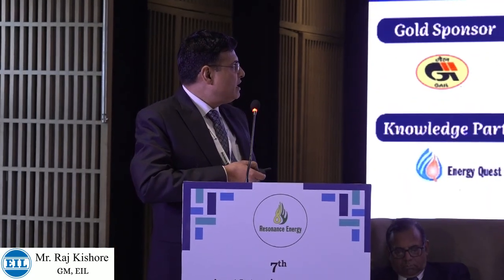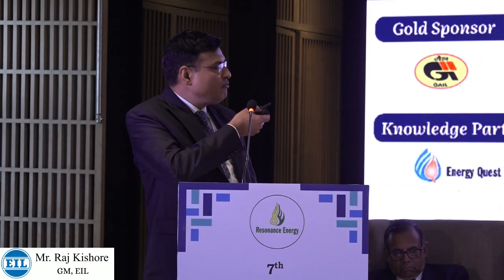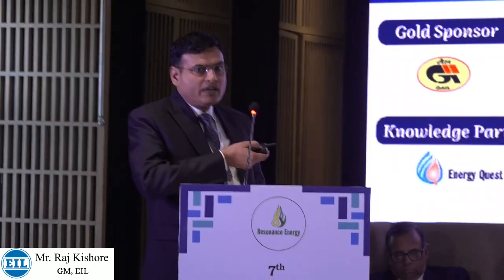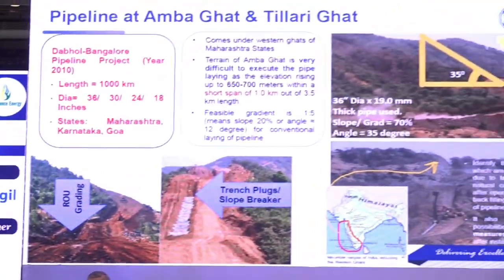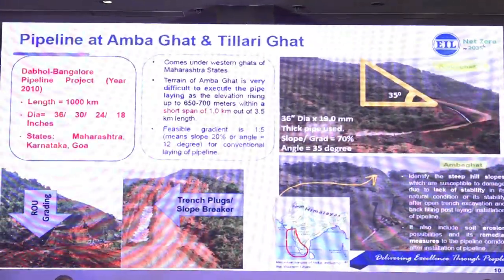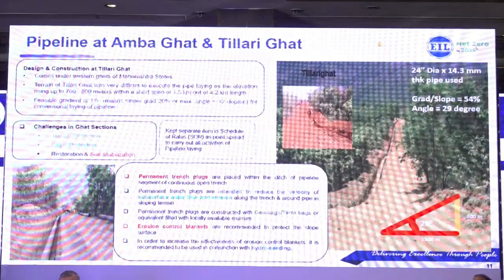Similarly, we did the same for Tilari Ghat. We selected higher thickness pipe and accordingly carried out the testing of the pipeline. For soil stabilization, if you see the previous slide, we installed trench plugs, or slope breakers. The actual dimension is 10 meters, but because of the slope the distance will be very less, and we installed those slope breakers and also other soil stabilization methods.